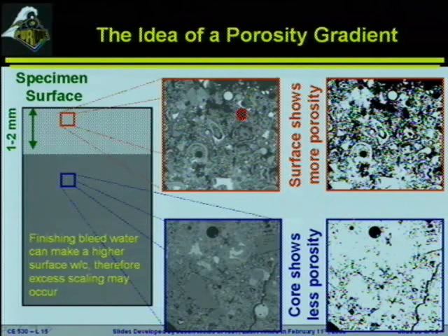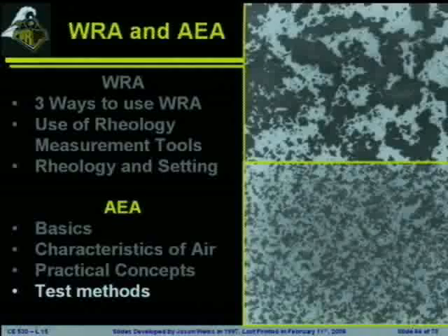So if we just look at the image to segment out the porosity, you can see that the bottom has quite a bit more white or hardened material than the top surface does. So there's a lot more porosity at the top surface. It's a lot easier for water to get inside of the system. One of the things that we actually looked into was the idea that you could reduce the porosity on the top surface by applying a little bit of a gentle drying that's taking place on the top. If you apply a little bit of gentle drying on the top surface, what will happen is the capillary forces will actually pull the particles together. You'll de-water the top part of the system and you'll make it much more resistant to scaling problem.